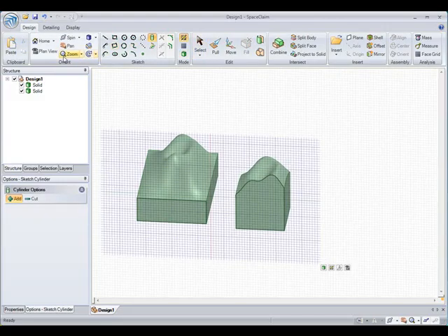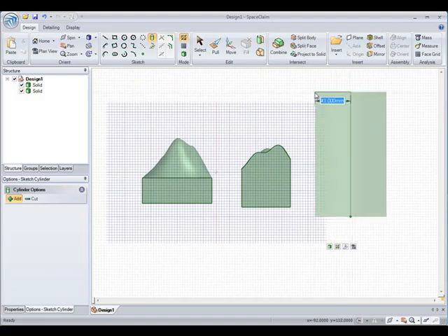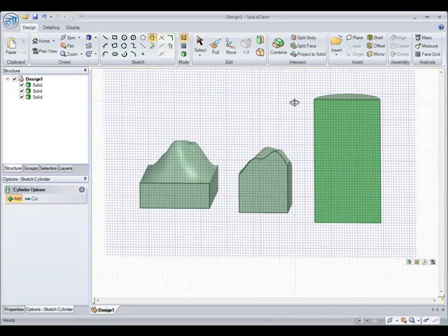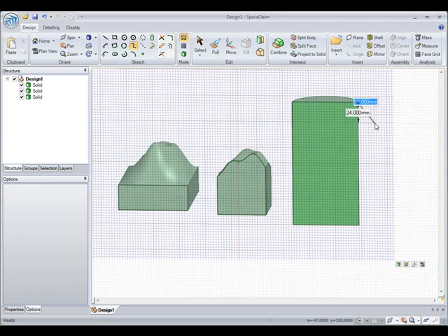So now I'll show one more example of using these blend lines to create a solid, and this time maybe we'll create a simple handle. So I'll make a cylinder, and now I'll use our guidelines, and I'll draw a straight line in the back, because I want to keep the back of our cylinder pretty much as cylindrical as possible, while I want my front to be a little bit more splined, and have indentations for your fingers.